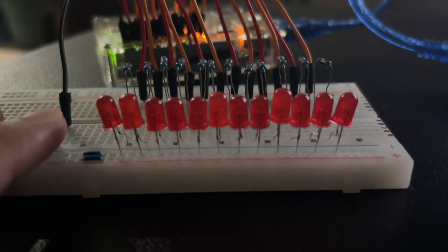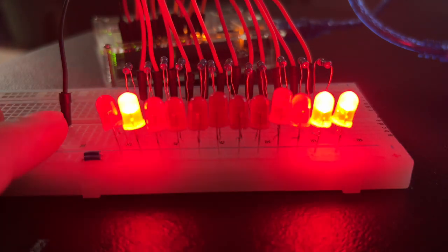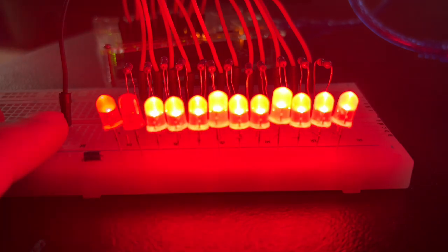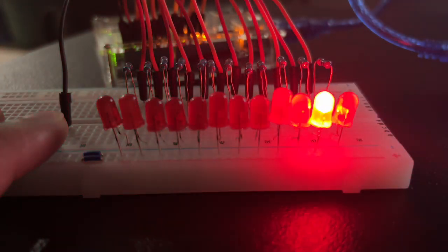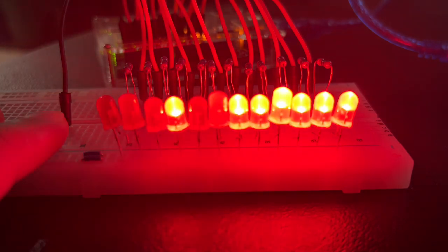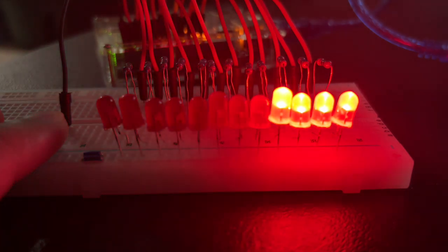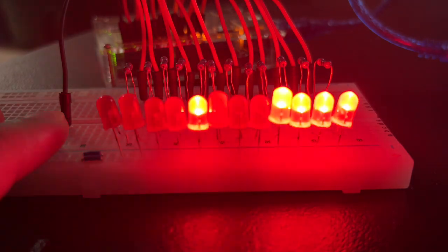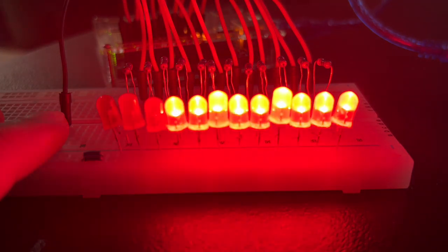While the tap switch is pressed, the program allows the LED sequence to run. The button is configured as active low. So when it is pressed, the Arduino detects a low signal and enables the animation. At this point, the LEDs follow the program sequence pattern, which continues to update at a fixed time interval.